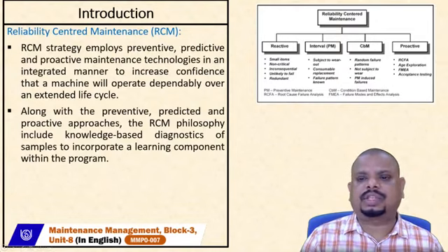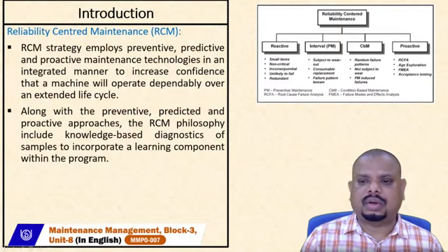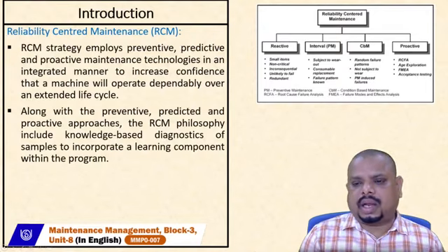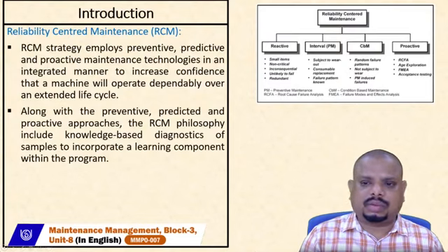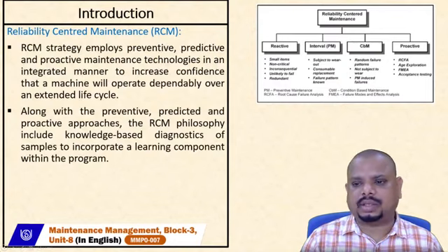Next we have CBM, which is known as condition-based maintenance, which identifies random failure patterns not subject to wear, and where preventive maintenance introduces failures. And the last class is known as proactive. In proactive, we implement RCFA, which stands for root cause failure analysis, age exploration.